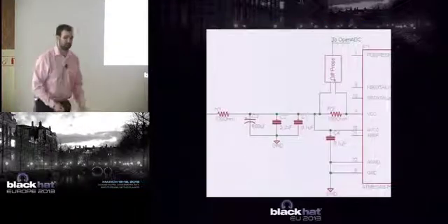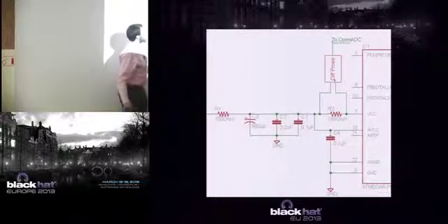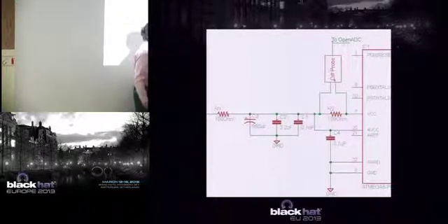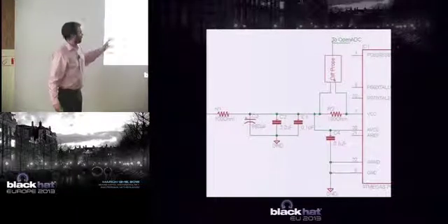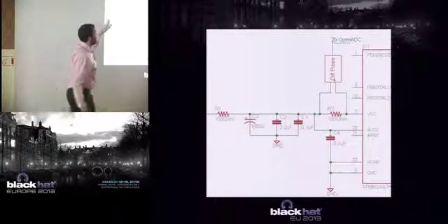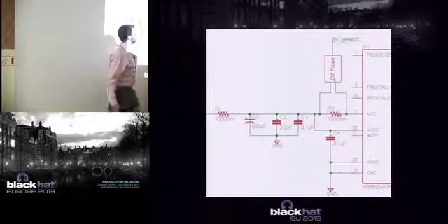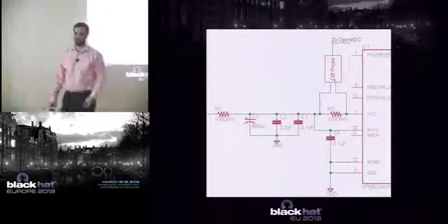So using a differential probe, the idea is that this common mode voltage will, to some degree, appear on both sides and be eliminated by looking differentially. I have to warn you, it's not quite perfect in this setup because the common mode voltage is not evenly applied to both sides. On one side, it goes through the resistor and is slightly reduced.